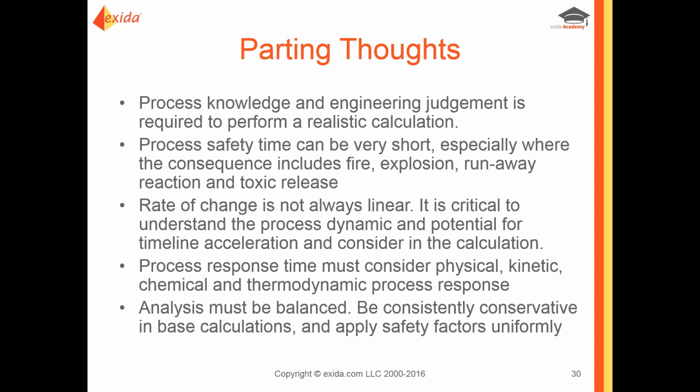The process safety time can be very short, especially if you're talking fire, explosion, runaway reaction, or a toxic release. It may be near instantaneous. So there may be more engineering judgment and less rigorous calculation in order to make that determination. But even if the numbers are determined from an engineering judgment perspective, they need to be based on what is occurring in the process and the process dynamics. In the examples that we did in this session, the rate of change was linear, but in the real world it is not always linear.